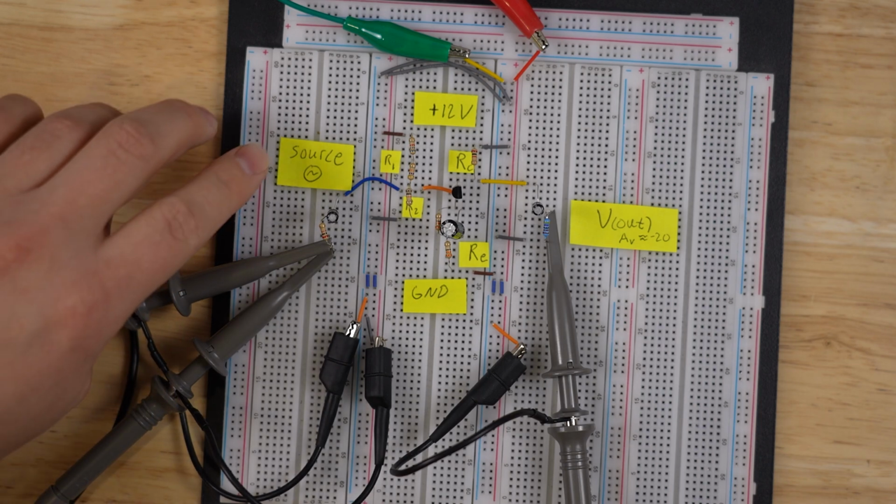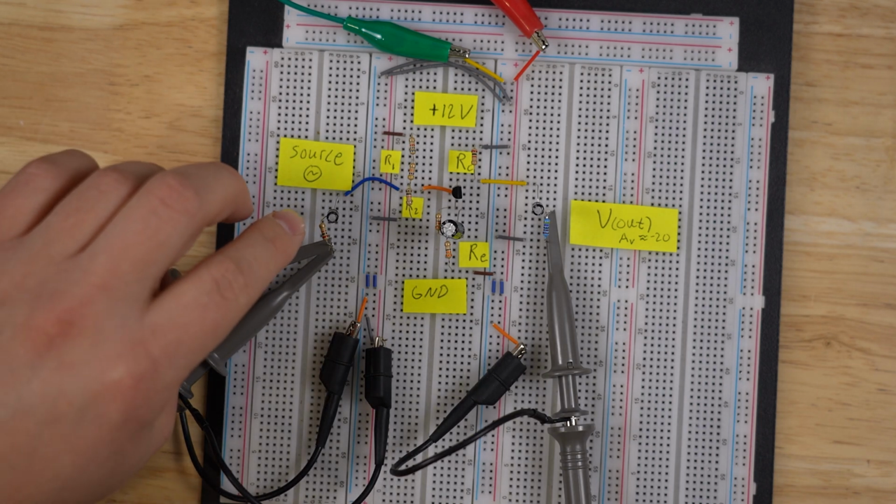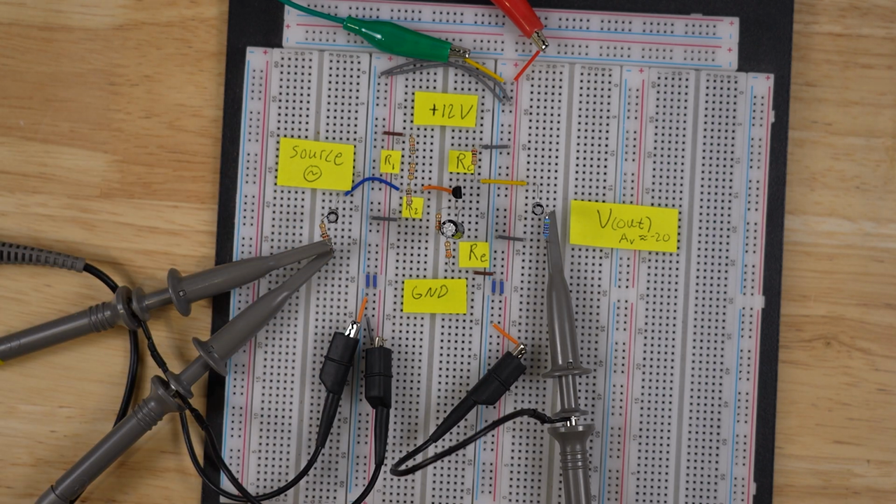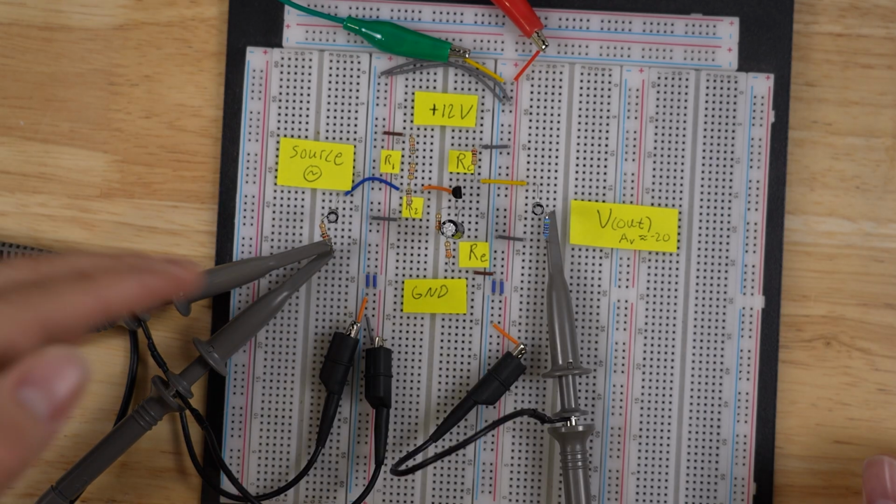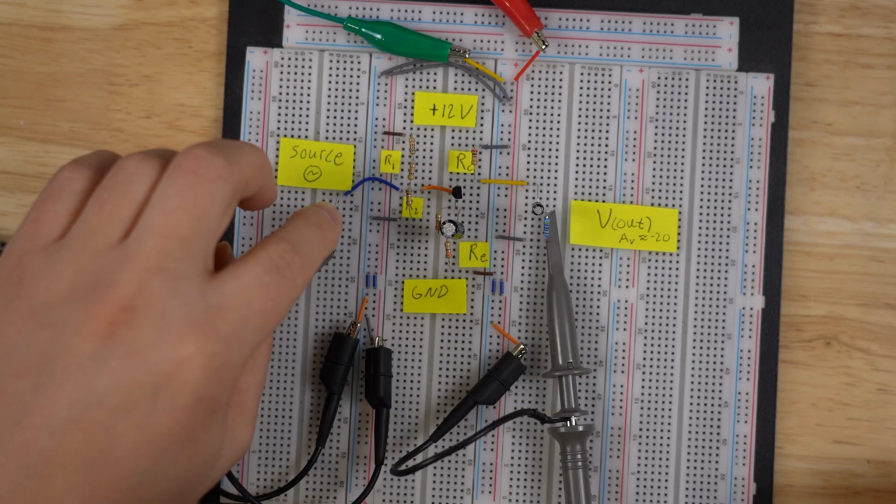So just a quick overview. We have our source over here on the left. There's a source resistor of 2 kilo ohms. The reason I have that is because I can set my function generator using this Analog Discovery 3 function generator to be 0 internal impedance or 50. So most function generators are 50. Keep that in mind if you're replicating this. So I have a 2 kilo ohm resistor for a source resistance.